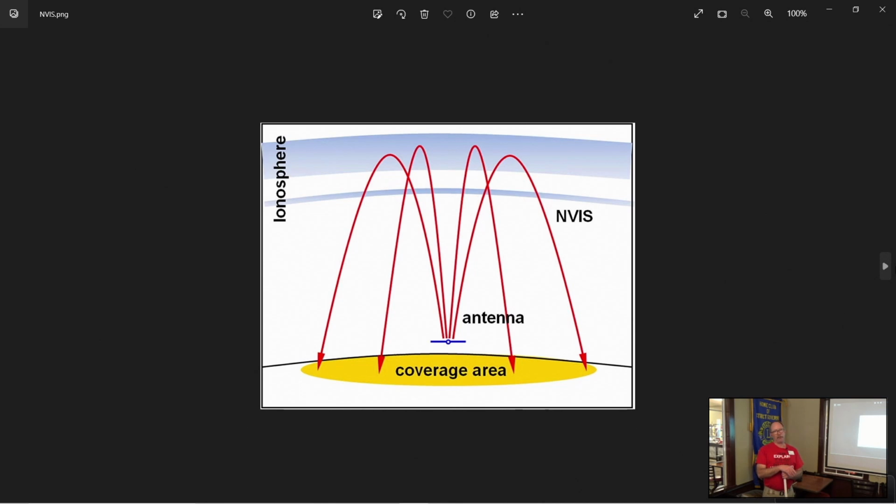By 9, 10 o'clock in the morning, usually, one of the ionospheric layers called the D layer starts to build up. The D layer absorbs RF. It is not our friend. That's why late at night, if anyone's ever been out in the middle of Nevada or Utah, driving cross country at night, you can hear KOA from Denver, 850 AM, on your car radio, because it does this. Come morning, it goes away. Even though they've actually increased power around sunrise, they're gone because that D layer absorbs that.